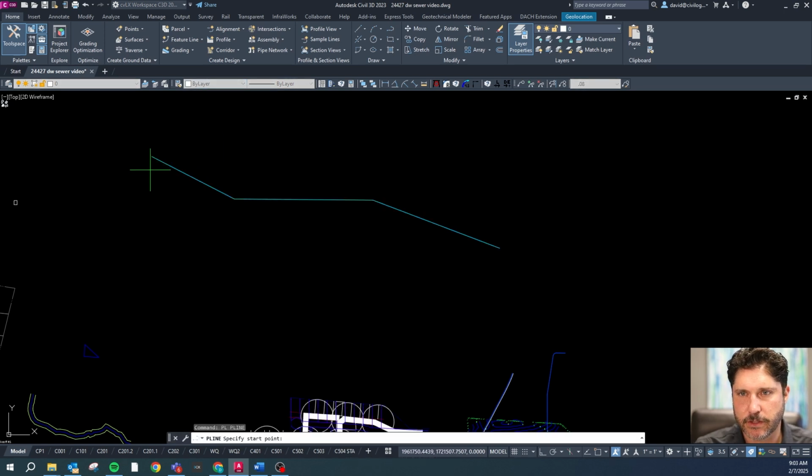We start 6 feet deep. Well, if we just go 1%, we're going to end up there, and that's not going to work because the pipe's not underground. So if we keep in mind the two main constraints of the minimum slope of 1% and the minimum cover, in this area of the ground, we're going to match the slope of the proposed ground so that we keep the minimum trench depth.